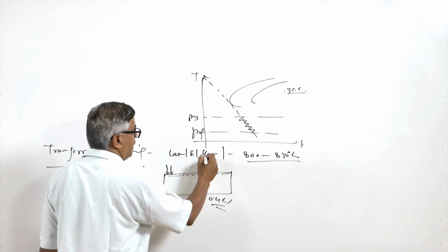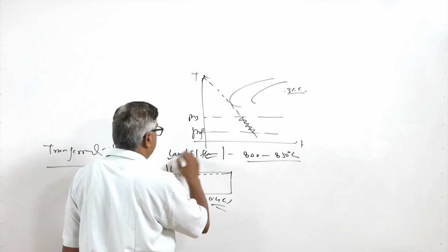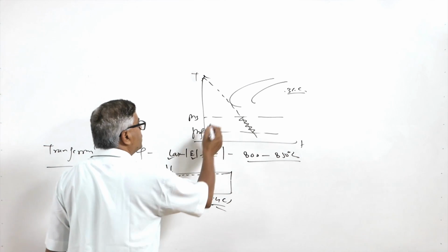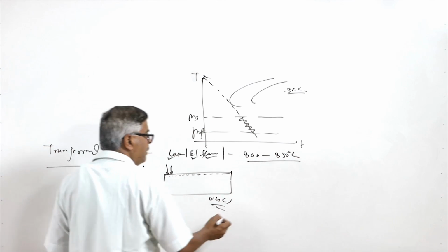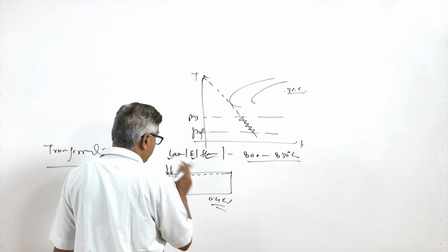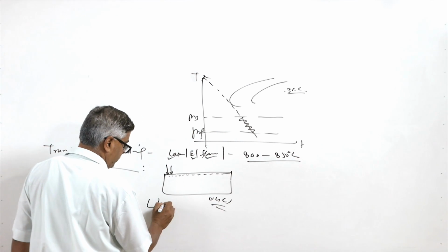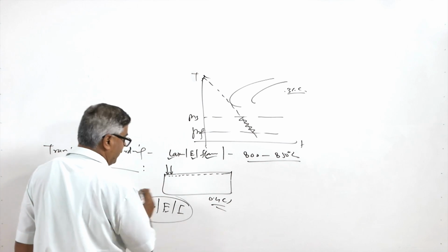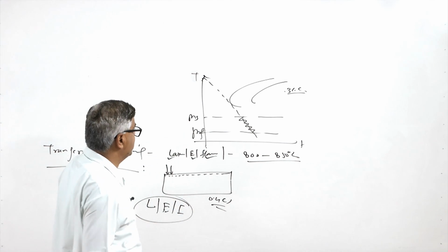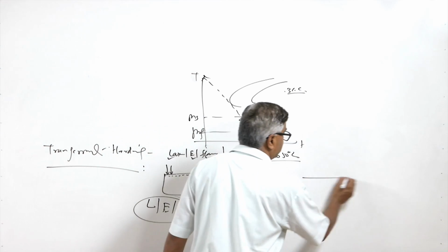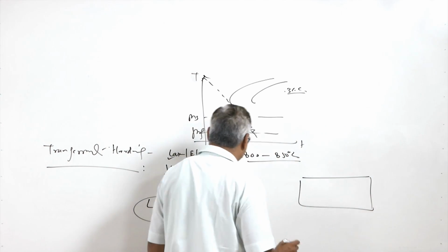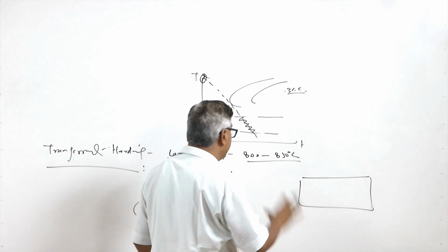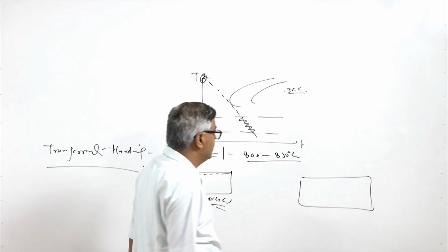For this, flame, electron beam, plasma or laser, anything can be used. Once this homogeneous austenite is formed, in case of laser, electron beam, and mostly induction hardening, no additional source of cooling is used, because the cooling under these conditions is so fast that austenite automatically transforms into martensite because of the high cooling rate.